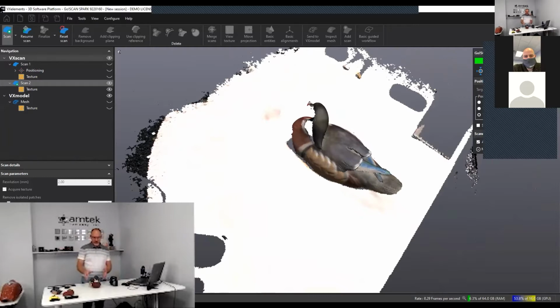In real life, if I was scanning this for an application, I would most likely be using something like modeling clay or some museum wax or even fixturing, which you could 3D print. And what I did when I scanned this to send off to Chris is I actually fixtured this model in a few different orientations, scanned around it 2 or 3 times, and then I used the software tools to merge these together so that it came out to a finished model.